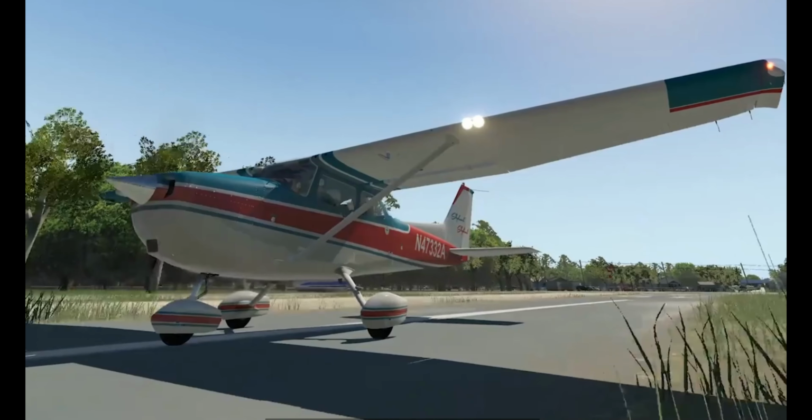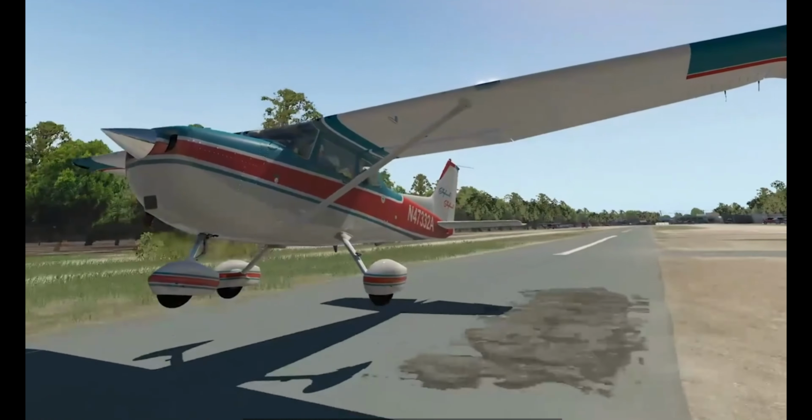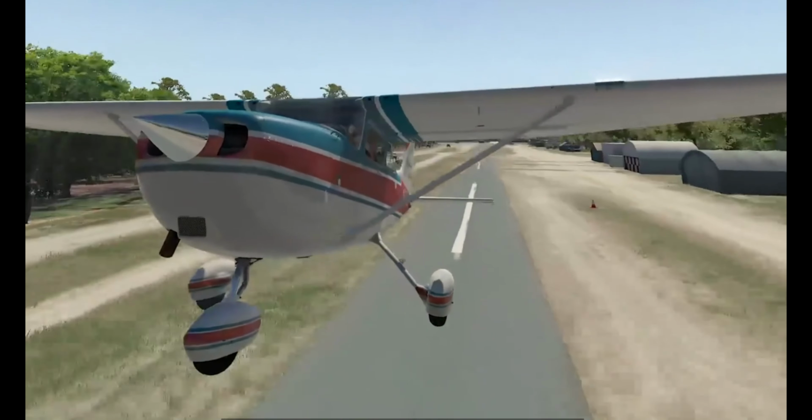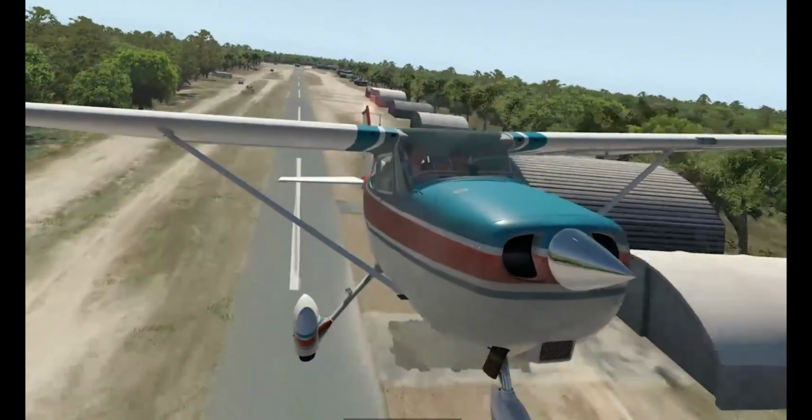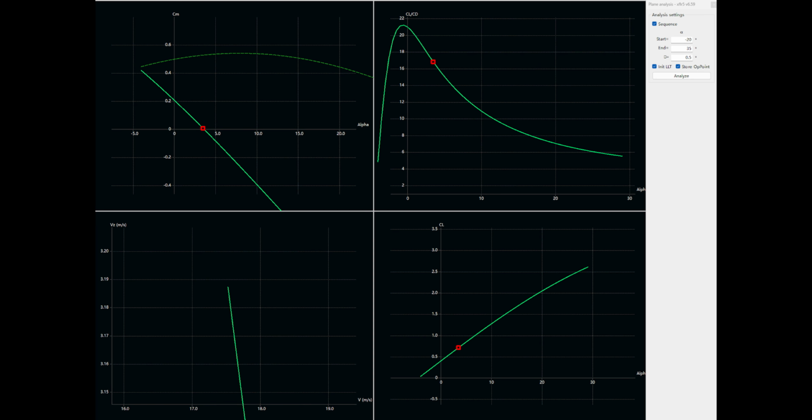Next, we further optimize the overall wing configuration, checking stability and improving flight performance. After entering the weight data, the center of gravity is located about 31 millimeters from the wing's leading edge. Using the point where the Cm-alpha slope approaches zero, the aerodynamic center is found to be roughly 280 millimeters from the wing's leading edge.